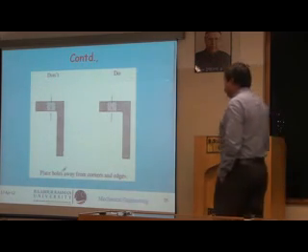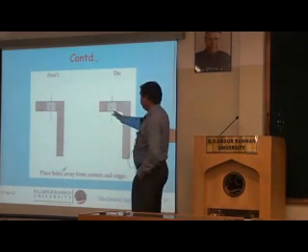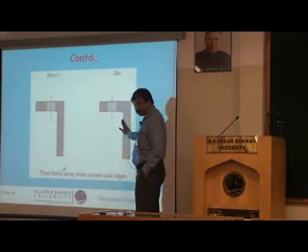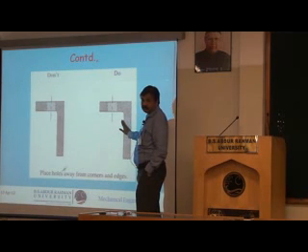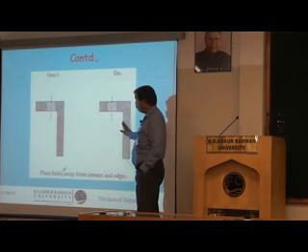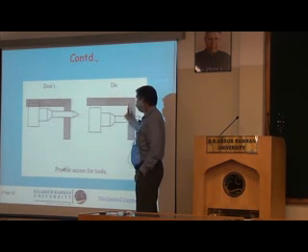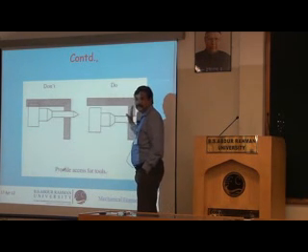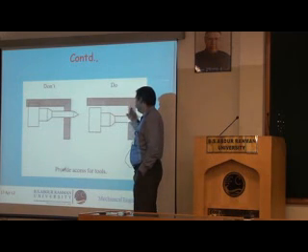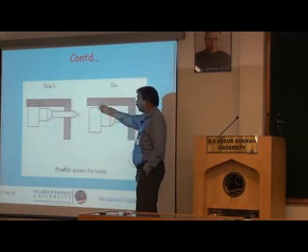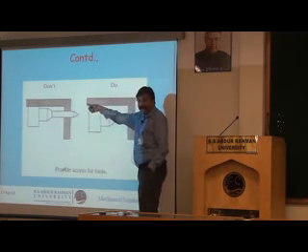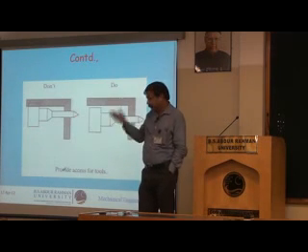Now, don't position the hole too close to the wall. That will be causing a lot of problems. Next. Because if it is too close to the wall, you cannot access it. You don't have access to this point. If you made a hole here, then you cannot access it. That head is colliding with your design. Next slide.